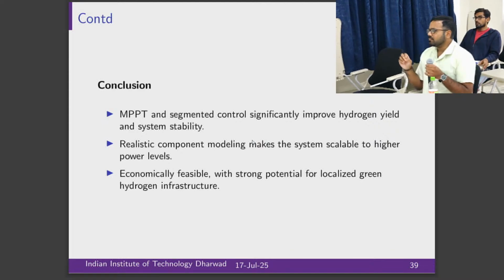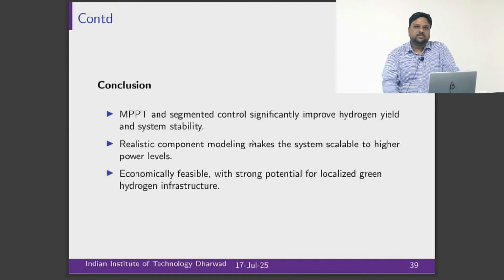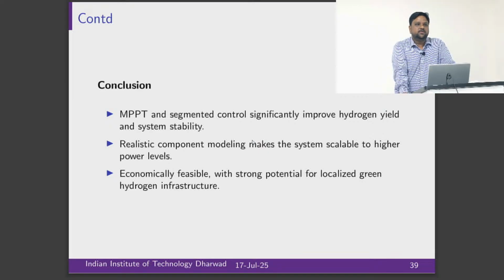Okay, so in this case, when I say flexible load, basically I consider it as a load. Load means it is only a sink of active power. But that sink is not fixed. Because you have power electronics and control involved, you can make that sink respond to frequency services. Let's say I have an AC/DC rectifier, an active front end rectifier. I want to control it as grid following or grid forming. From there I can control my active power consumption based on the grid frequency.